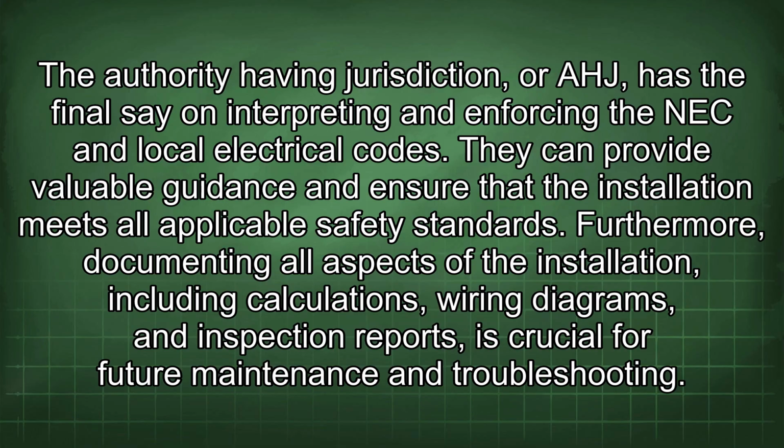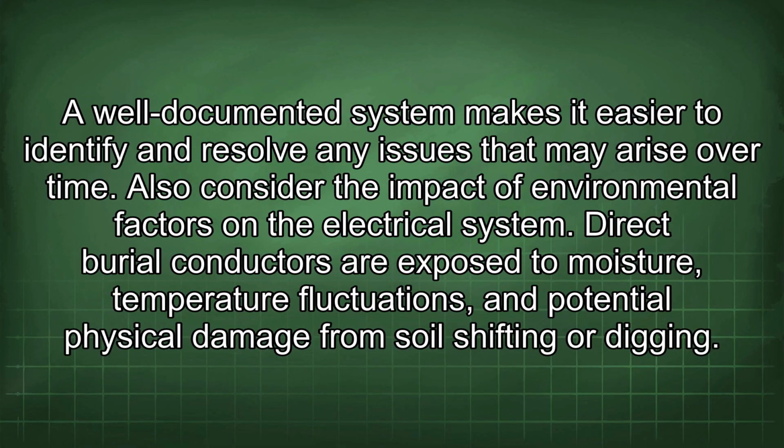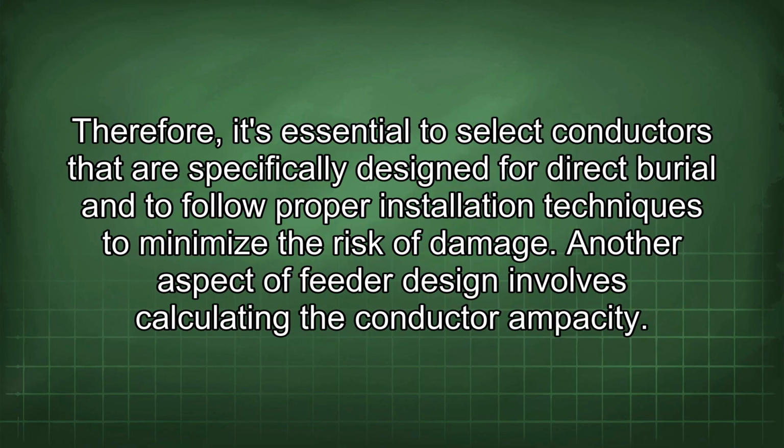Furthermore, documenting all aspects of the installation, including calculations, wiring diagrams, and inspection reports, is crucial for future maintenance and troubleshooting. A well-documented system makes it easier to identify and resolve any issues that may arise over time. Also consider the impact of environmental factors on the electrical system. Direct burial conductors are exposed to moisture, temperature fluctuations, and potential physical damage from soil shifting or digging. Therefore, it's essential to select conductors that are specifically designed for direct burial and to follow proper installation techniques to minimize the risk of damage.